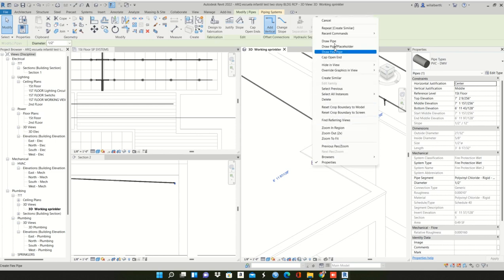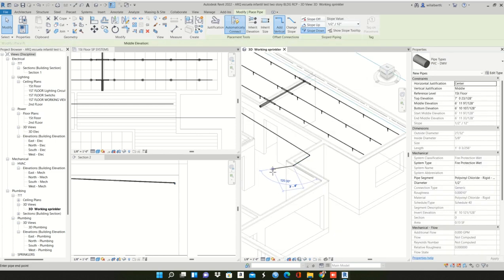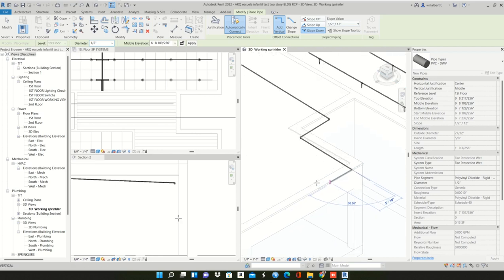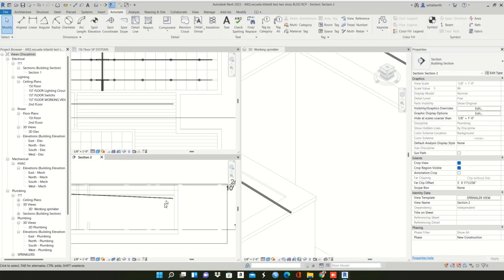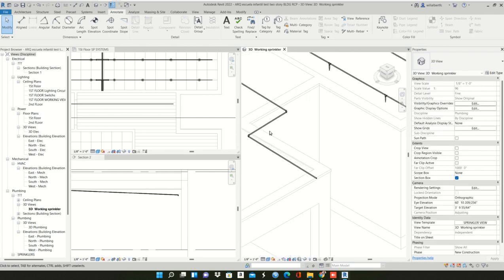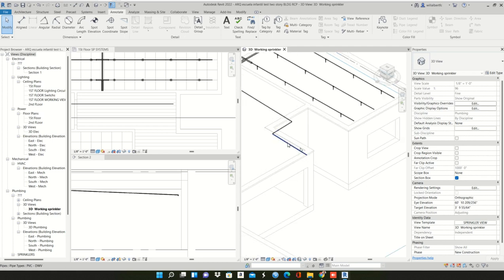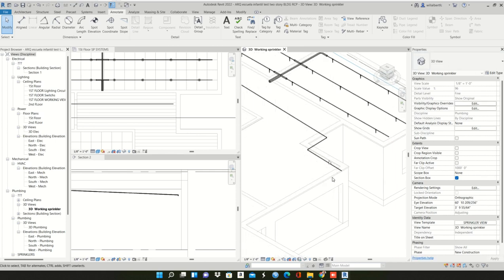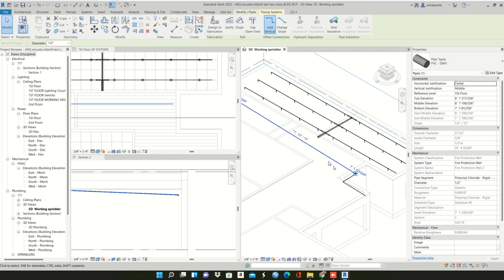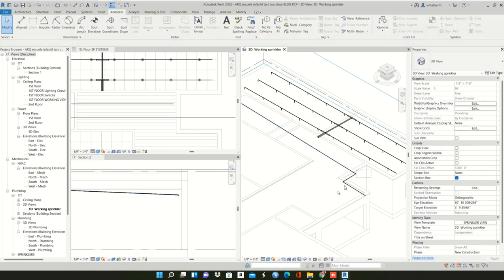So you can create here. Let's suppose that we have to go further in this wall. I have to press shift to work in 90 degrees. By doing that, I will be sure that I am making a snap on that horizontal axis. So that's how the slopes work. We will practice this more in the future because you will need it when you are making plumbing designs, but I wanted to show you how it works.